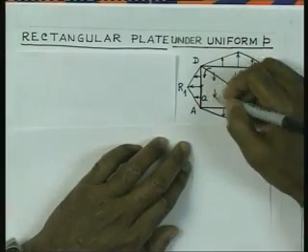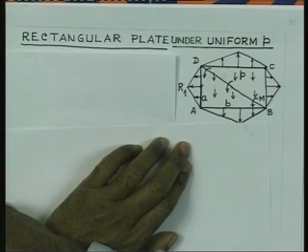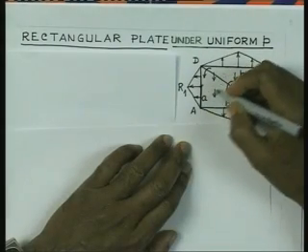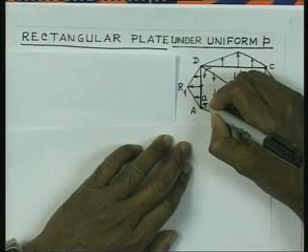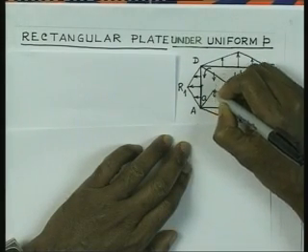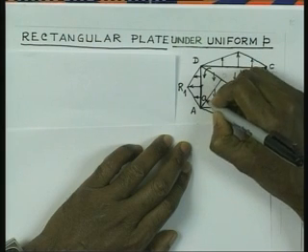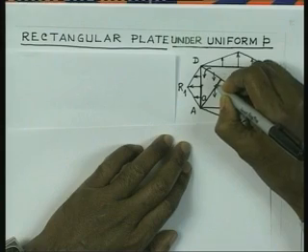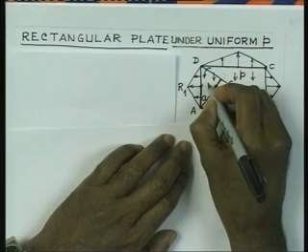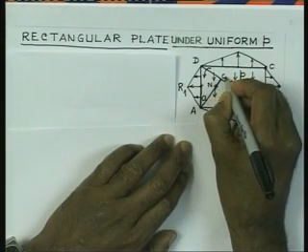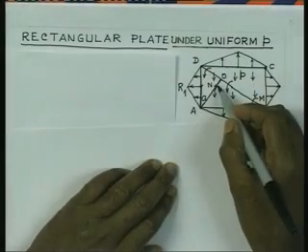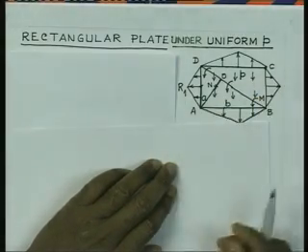Now, the external loading, which is uniformly distributed pressure over the triangle ABD, it is going to have its center, if we drop a normal here on this diagonal, at 1/3 of the height somewhere here we are going to get the center of the loading. So, therefore, this ON is the distance of this CG of the distributed pressure.